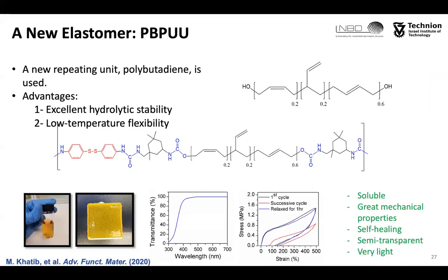So as a first step to reach this ultimate goal, we have introduced a new self-healing thermoplastic elastomer for use under harsh and complex humidity and also under water conditions. More specifically, we have synthesized a new polymer from hydroxyl-terminated polybutadiene that, as you can see, is extended by isophorone diisocyanate and 4-aminophenyl disulfide. And we have done it by 2 reactions.